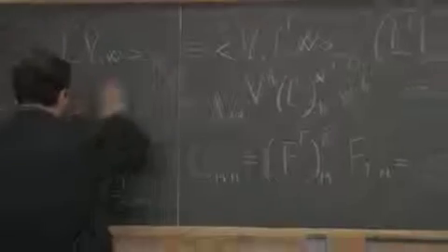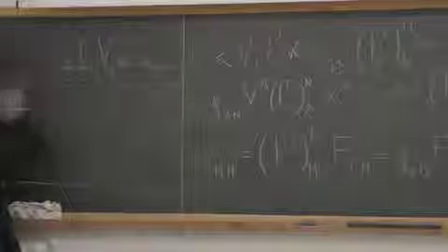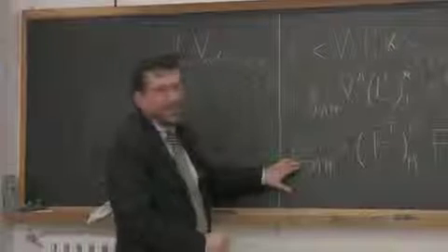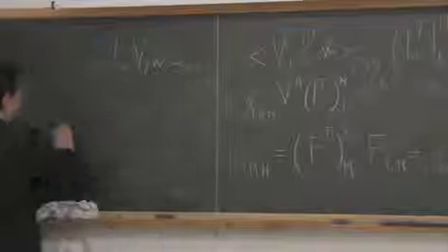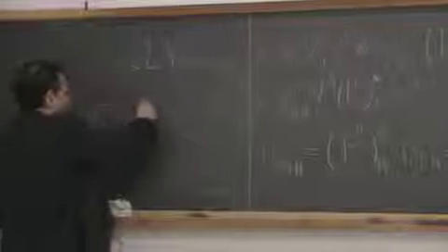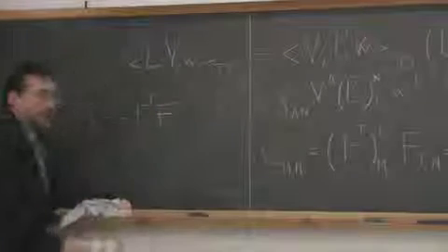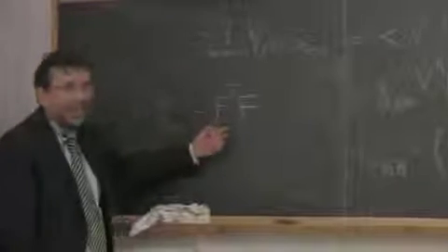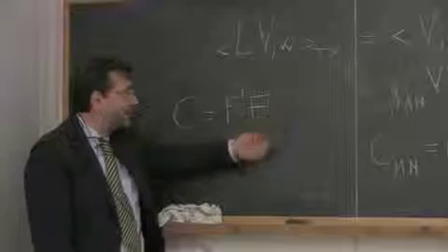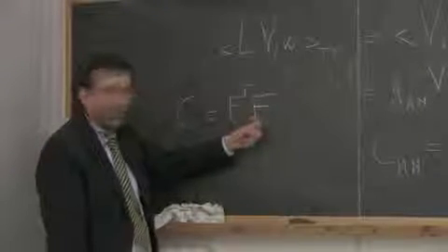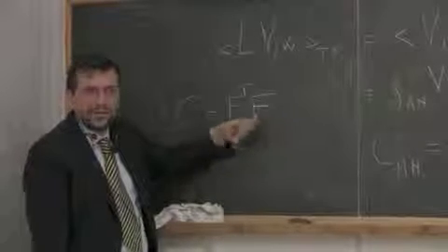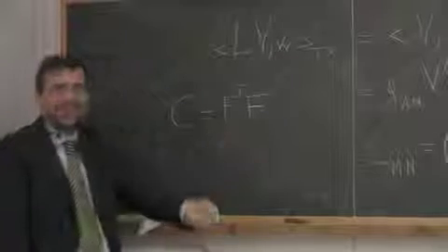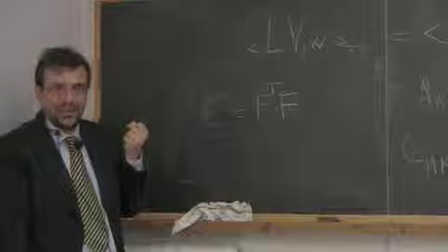Next step is here. With some pain, we have discussed in a previous lecture that the right way for measuring deformation is considering F transposed F, which is very elegant, because you take a vector V, you apply F, you get a small Eulerian vector. Then you apply F transposed, and you have back a Lagrangian vector.